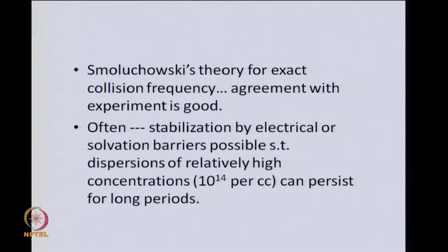So, if the particles are present, it is a heterogeneous nucleation. If there are no extraneous particles, dust particles or roughness on the surface or seed crystals, then we have only the solvent and the solute. And if such a system has to form nuclei spontaneously in these very clean systems, you need very high supersaturation. In crystallization literature, you would come across supersaturation to the tune of say about 1500% over saturation. You require that high supersaturations in order to have any crystal nuclei forming. And that is homogeneous nucleation. So, homogeneous nucleation is in a very clean system, heterogeneous nucleation where there are some seed nuclei to build up the nuclei. Now, we are returning to something which is colloidal particles which have very high energy.